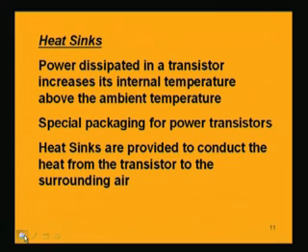So these are special packagings for power transistors, which incorporate a heat sink, and this heat sink is bolted to the transistor, which is again inside a case. So the device will be packaged first with a case, and that case will be bolted into the heat sink.